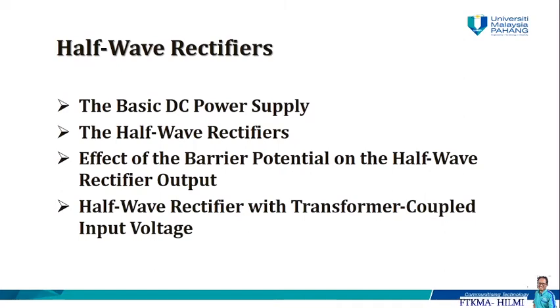Next is the half-wave rectifiers. In this topic, we are going to cover the basic DC power supply, the half-wave rectifier itself. We are going to learn about the effect of the barrier potential on the half-wave rectifier output and the half-wave rectifier with transformer coupled input voltage.